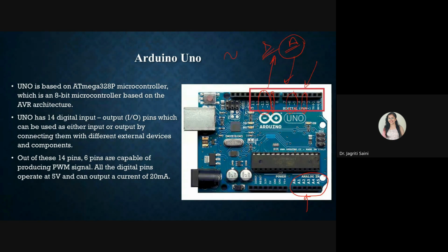So you can use any of the pins from the digital world. But when I talk about brightness level change on your LED, like I need a dimming effect on the LED, that you can do with the PWM pins only, because that only can translate your brightness levels into different thresholds. So this is how different pins may help you to make different decisions.